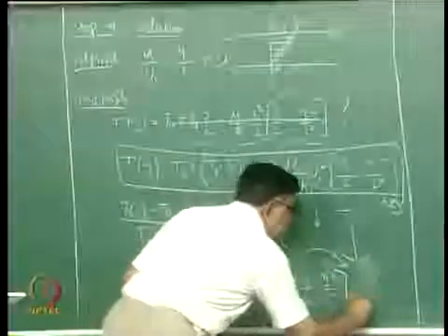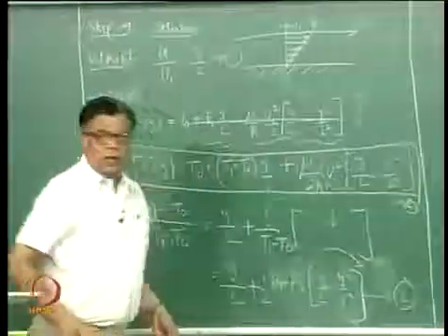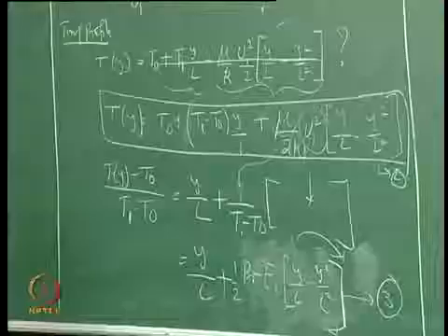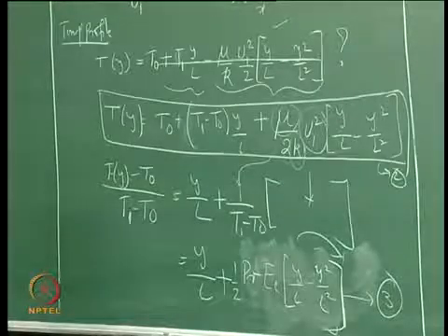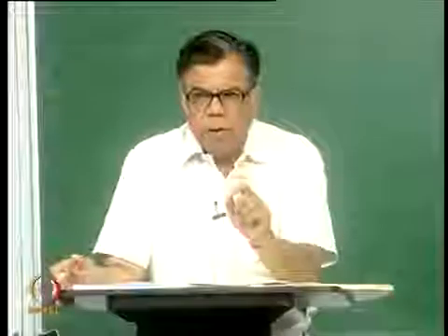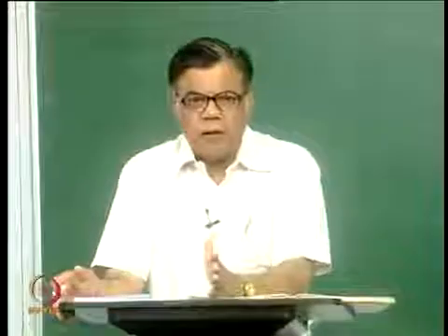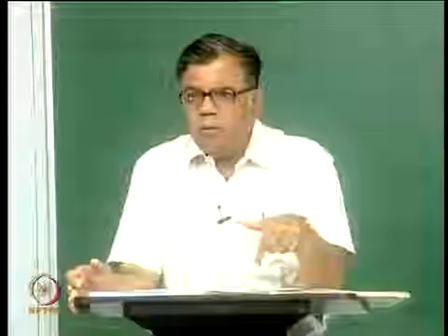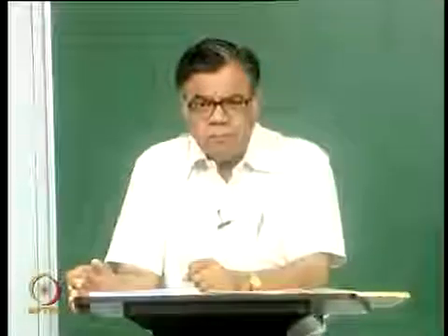You do not have to do that, but this gives you a new non-dimensional number you can see visually, and you also realize that it is important only when u1 is significant. u1 can be 0, then it is not significant. u1 can be a very small value, it has its own role, but you also know it changes with u1 square. So from 5 meters per second u1 you go to 10, the effect is squared actually.